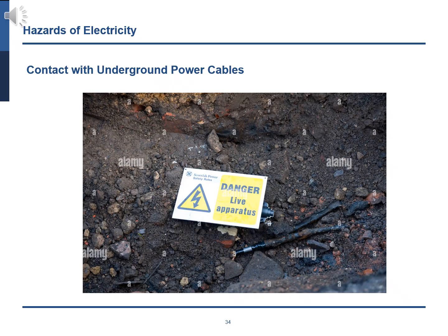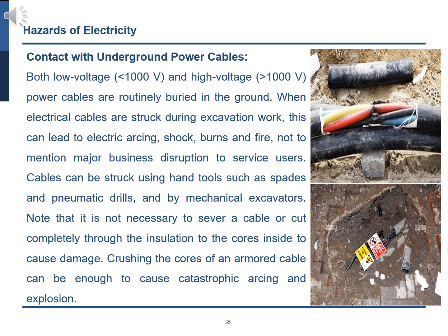Contact with underground power cables. Both low voltage, less than 1000 V, and high voltage, greater than 1000 V, power cables are routinely buried in the ground. When electrical cables are struck during excavation work, this can lead to electric arcing, shock, burns, and fire, not to mention major business disruption to service users.